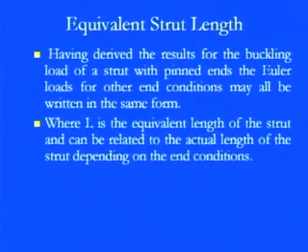Now we are interested in calculating the equivalent strut length. Having derived the results from the buckling load of a strut with pin ends, the Euler load for other end conditions can be written in the same form, where L is the equivalent length of the strut and can be related to the actual length of a strut depending on the end conditions.